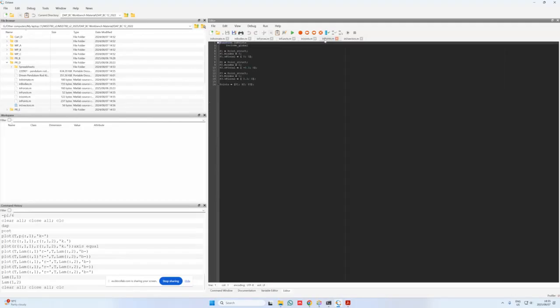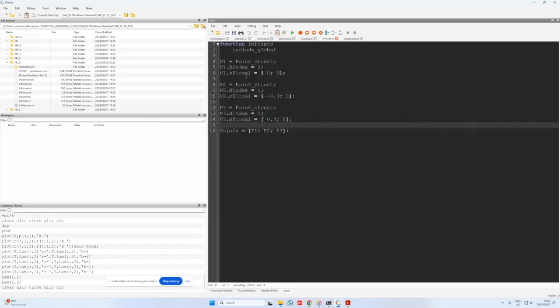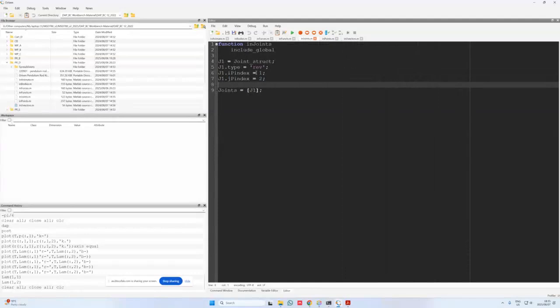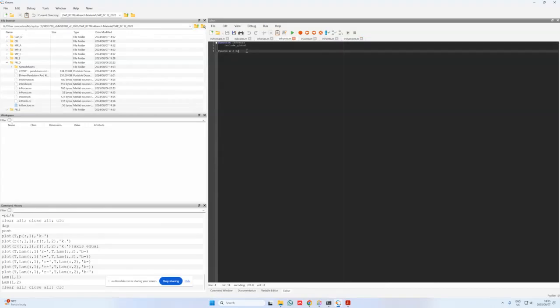For the endpoints, it also remains exactly the same. So I have 3.2 of the point 1 is specified on ground, points 2 and 3 are specified on the pendulum rod. In joint is now still the revolute joint, so I don't enforce any other joints at this stage. In U vectors is still an empty vector that I have over here. In functs, I'm going to leave open for now.